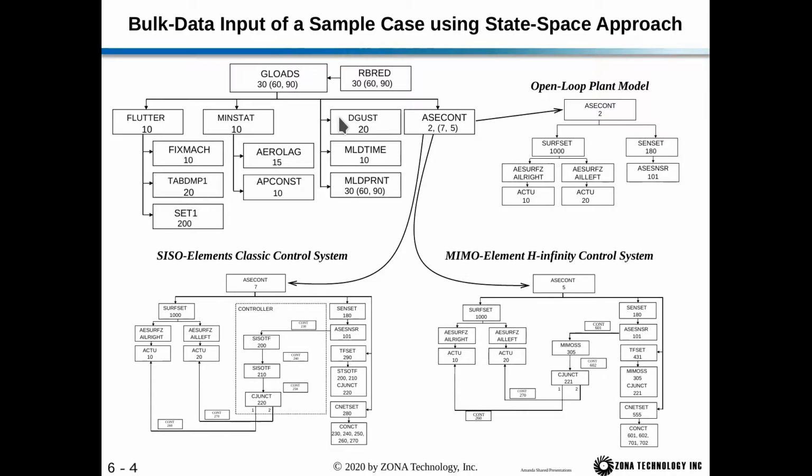For the new cards, we have the D-Gust card to define the gust parameters, and then we have the MLD time card to define the time parameters of time integration during simulation, and the MLD print card to output parameters of interest from the time simulation.